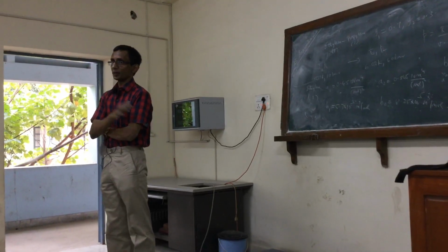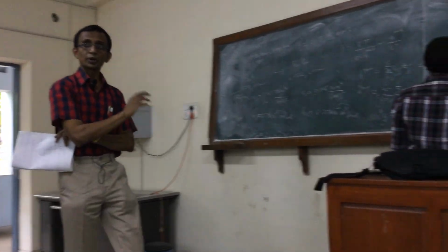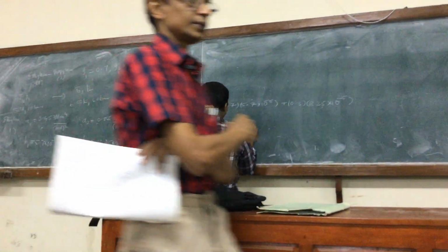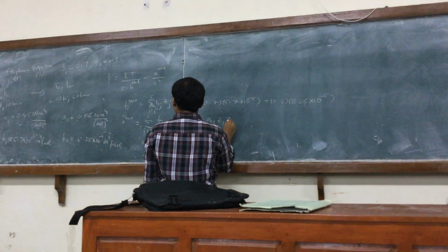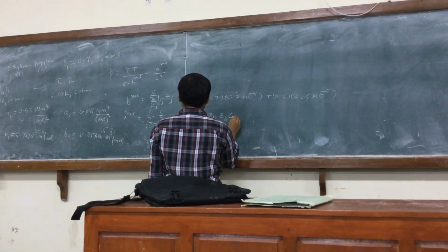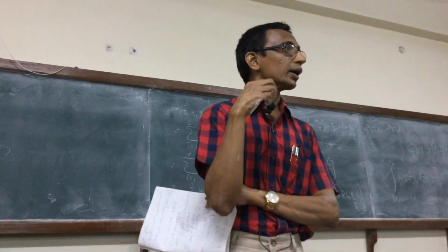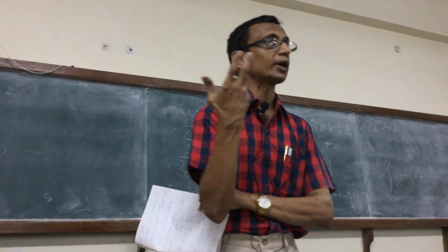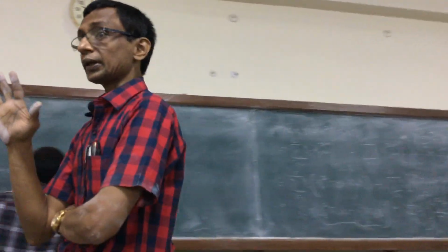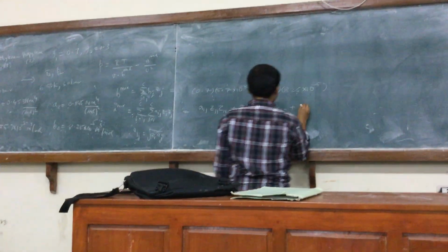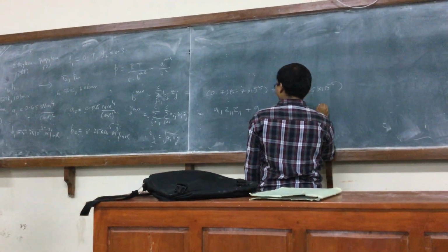For a binary mixture there will be 4 terms. For a C component mixture there will be C times C terms. Right? So you have to be very careful. But for a binary mixture, A12 and A21 would both be equal, and they would be equal to square root of A1 times A2. So this makes the calculation of A slightly more complicated.